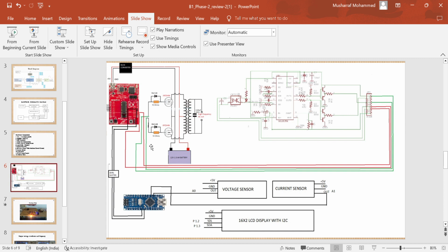This is the optocoupler. The optocoupler is used to isolate the MSP from the inverter, and that is its main purpose. I see it also helps prevent backflow of power, which would damage the MSP while performing iterations. These signals are given to the optocoupler, and from there to VCC and S0. On receiving signals from the MSP through the optocoupler at VCC and S0, the SG3525 will generate